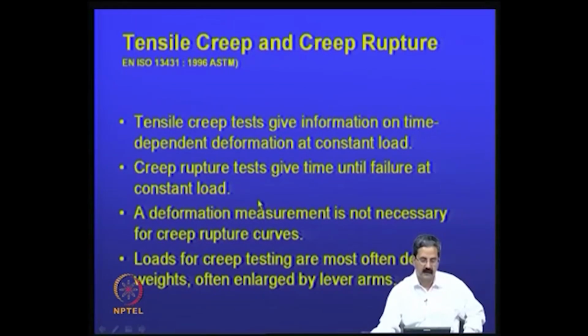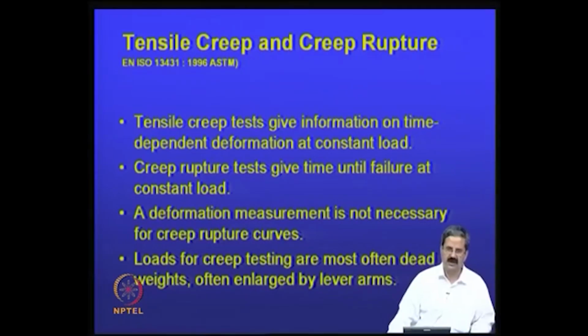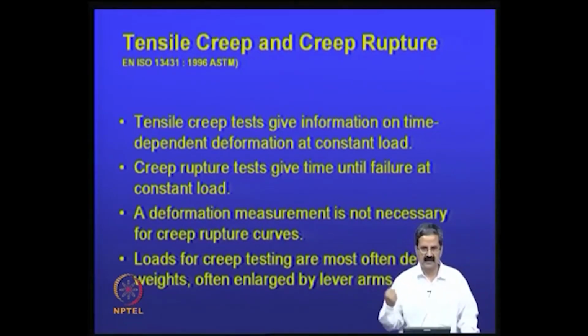The other important property is called tensile creep. You are doing a tensile test, but you apply the same load, and still there is a creep. Tensile creep is an important parameter; it gives information on the time dependent deformation at constant load, and sometimes the material also fails. This is called rupture. You keep on pulling with the same load, and because of the molecular arrangement, as I just mentioned, there is a deformation that occurs over time even if the load is the same.